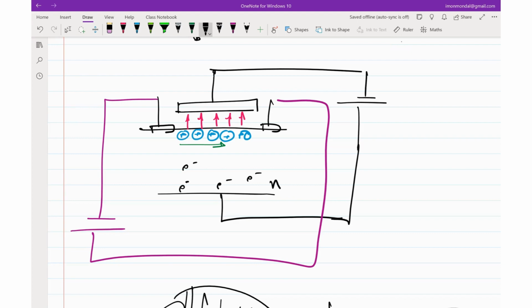The way we ensure that is as follows. In this piece of silicon, the primary carrier transport is due to electrons. So I carve out a place here. Another important piece of information is that it's not as if you simply connect the metal on top and it's going to work. You have to dope that area with either an N-type impurity or a P-type impurity. I haven't talked about a P-type impurity as of now.